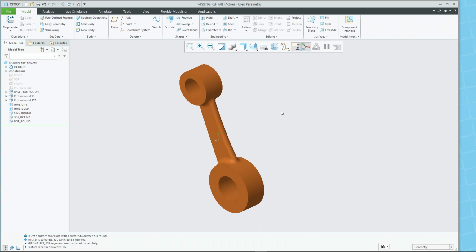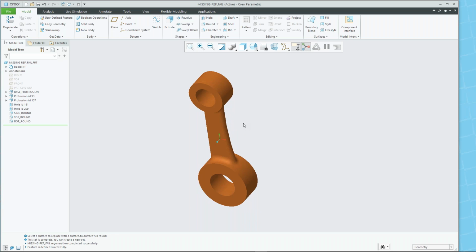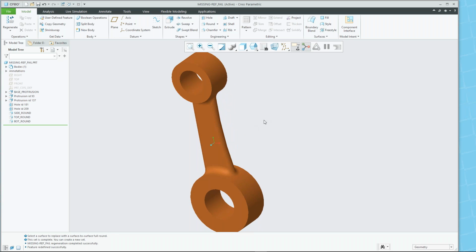It's just, once again, getting familiar with some of the tools inside of Creo, and what functionality you can use. So it's always a good idea, if you're not sure immediately what the problem is, to remember that, like I said, it could be the feature directly that you're working on, like it was with the chamfer, or it could be a prior feature that's causing a problem. The feature itself regenerated, but some subsequent child feature may fail regeneration because of something I changed in the original feature.